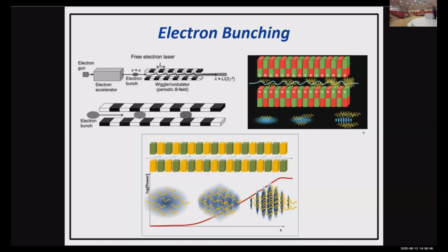What about the phase of the electromagnetic radiation coming out of this type of experiment? Are they phase locked? Oh, it's really a random phase. Pulse to pulse it's very random, if you are talking about oscillators, of course. If you talk about amplifiers, they will lock with the seed signal. If you have a solid state input injector, you can control the phase to some degree. But for oscillators, free running oscillators, it is random.